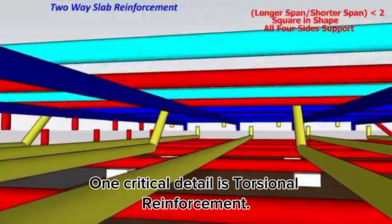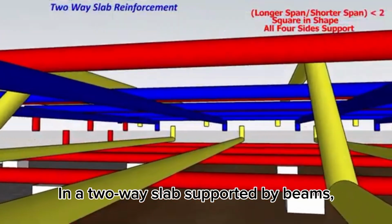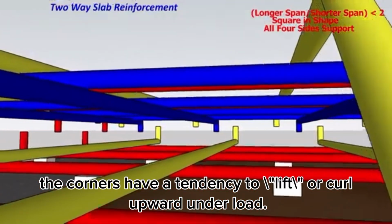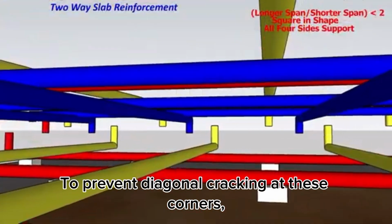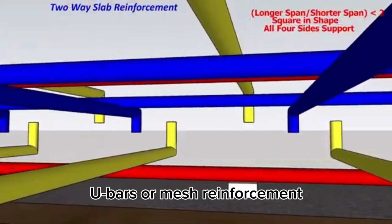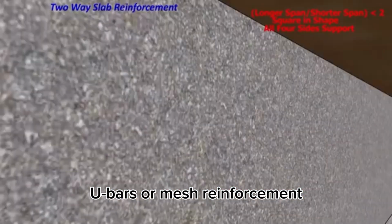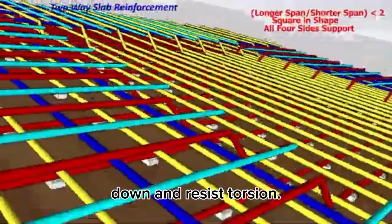One critical detail is torsional reinforcement. In a two-way slab supported by beams, the corners have a tendency to lift or curl upward under load. To prevent diagonal cracking at these corners, engineers specify additional U-bars or mesh reinforcement at the exterior corners to tie the slab down and resist torsion.